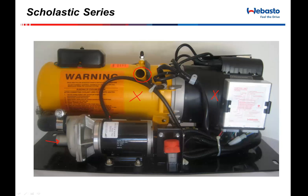That process will continue until the water temperature in the heater hits approximately 175 degrees. On a cold-soaked conventional chassis, with a bus cold-soaked to around 0 degrees Fahrenheit outside, going from 0 to 175 should take approximately 30 to 35 minutes.